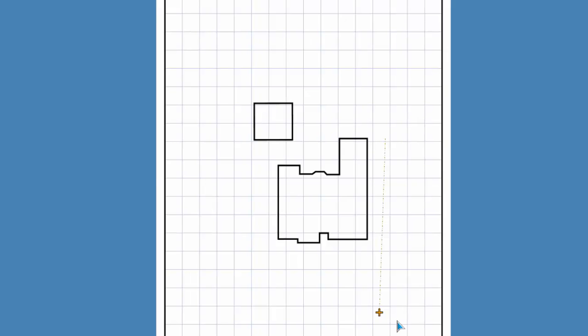I start the line command again and press the A key to reset the anchor point location. Snap back onto a corner of the house. I press the up arrow key to open the point polar command, enter a value of 47.1, and press the enter key. I press the A key and snap onto another corner on the back of the house, press the up arrow key and enter a value of 62.1 and press enter. I press enter again to end the line segment.